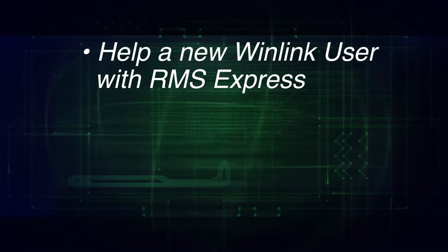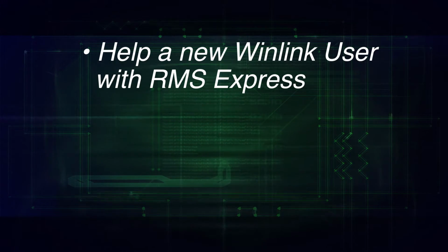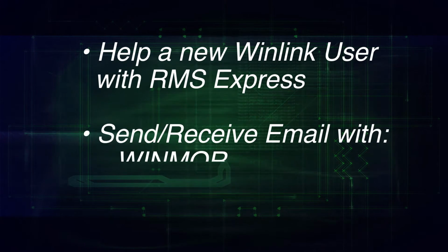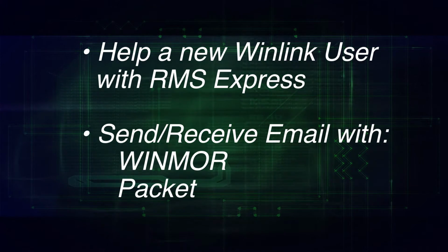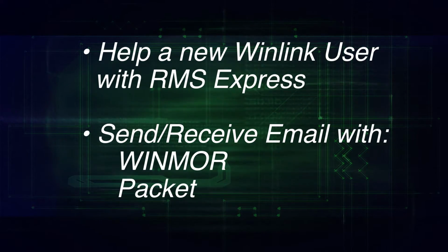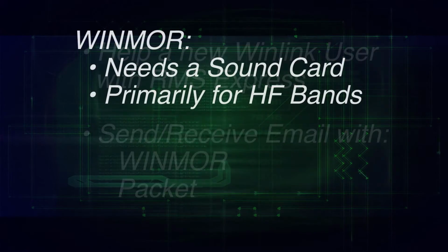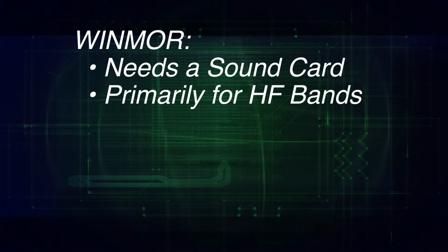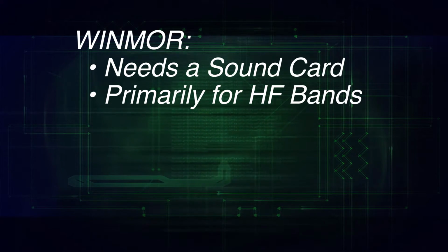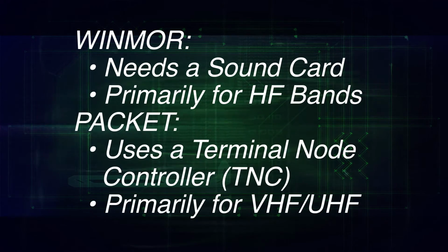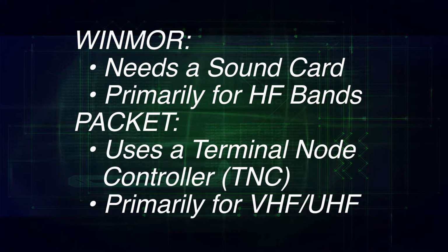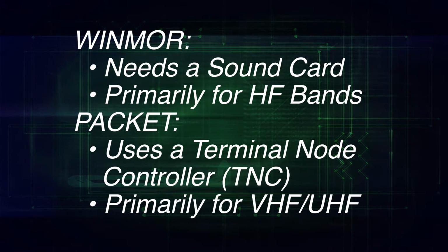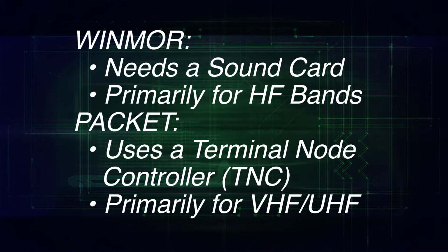The purpose of this video is to get a new user up and running with the RMS Express application for the WinLink system and show how to send and receive email messages using the Winmor and Packet digital modes. Winmor needs a sound card and is used primarily for the HF bands. Packet uses a TNC, which is an abbreviation for a hardware terminal node controller, and is primarily for VHF and